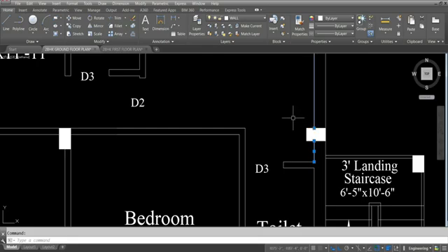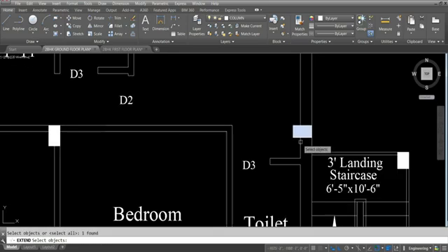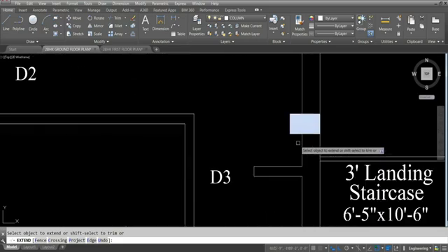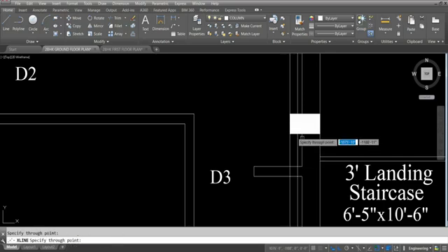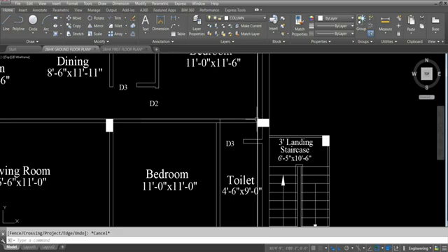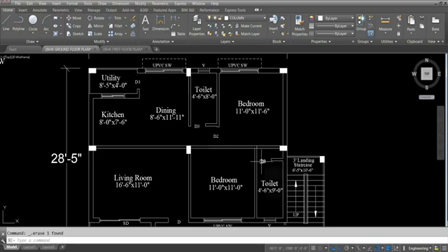We have done. Okay. Now we will extend the wall line to here, to this point. So for that, we cannot extend here. It is, we have done block. Okay, we cannot extend, so we have to take a construction line or a line to this line. I'll take a construction line, Xline, vertical line here. Now I'll extend, select this and extend this wall lines. Okay. Now I will delete the construction line. This is no longer required.